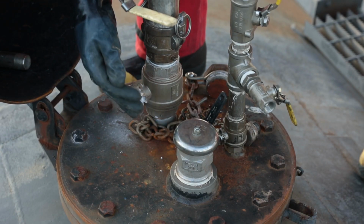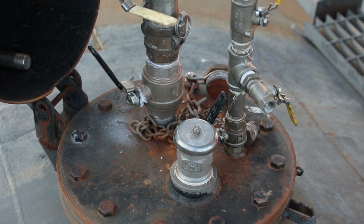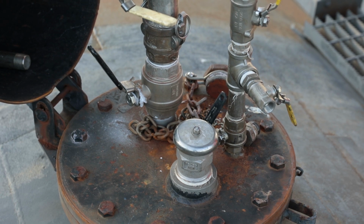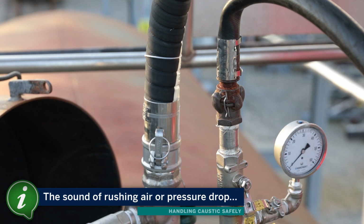Slowly open the eduction pipe outlet valve to flow the caustic soda to the storage tank. Check for leaks and shut down the unloading process for repair if necessary. The sound of rushing air or a drop in pressure can indicate that the tank car is empty.